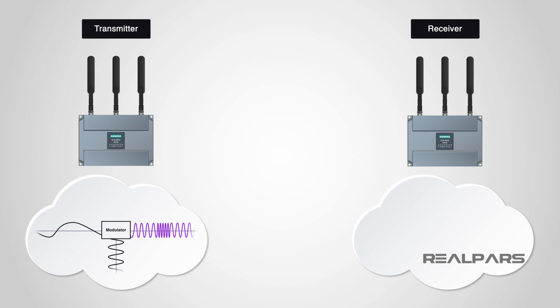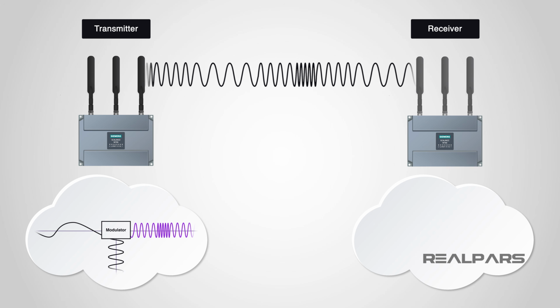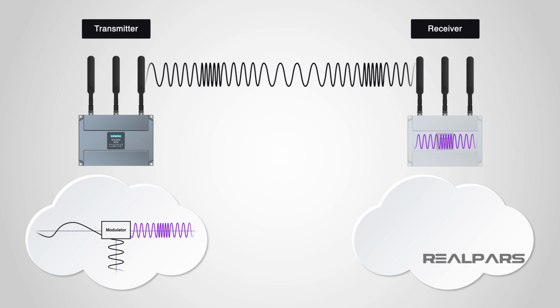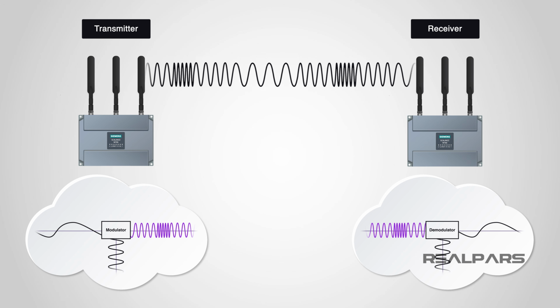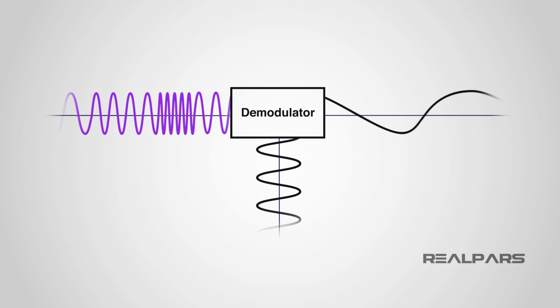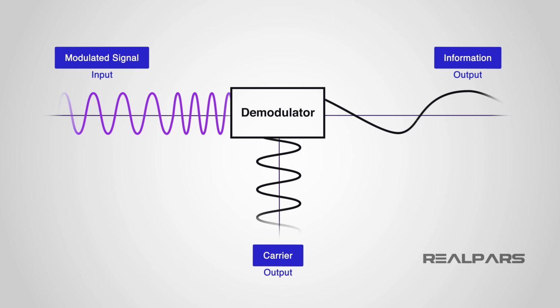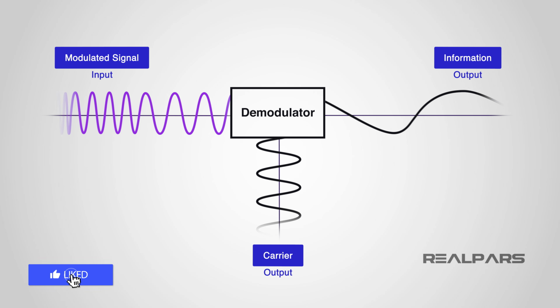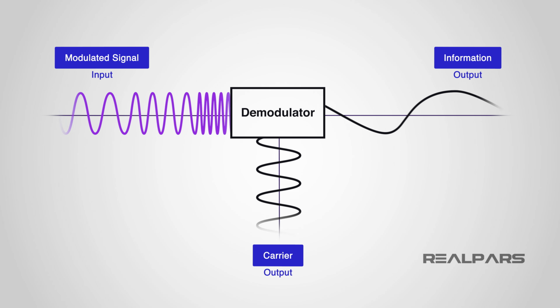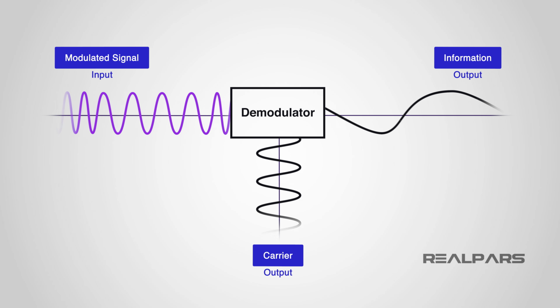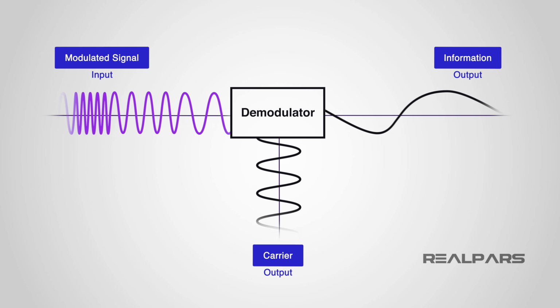And as we have learned previously, the transmitter sends the modulated and amplified signal to the antenna, which is specifically designed to emit this signal into the air. The now modulated and amplified signal, which emanates from the antenna, propagates through the air towards the receiving station antenna, where the modulated signal is demodulated, separating the data from the carrier signal. So, in other words, modulation alters the shape of a carrier wave to encode the speech or sound and data information we want to be transported by hopping on a normal signal wave.